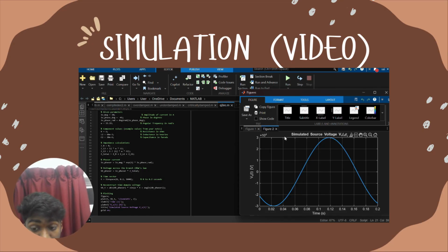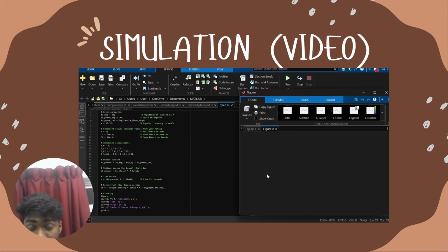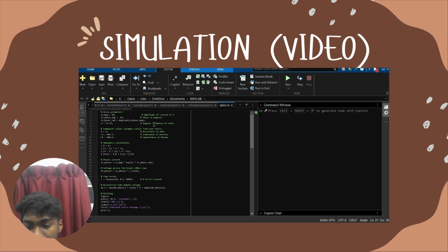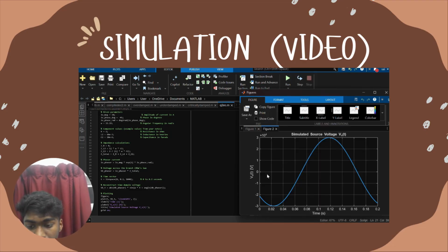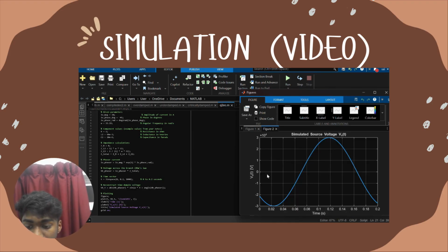In this specific simulation run, we used a standard capacitor value of 20 microfarad on line 9 of the code. In our hand calculation, we used a much larger capacitor, which is 20 millifarad. Since the impedance is ZC, a capacitor 1000 times smaller creates an impedance 1000 times larger. This is why the simulation voltage is roughly 1000 times higher than the hand calculations.